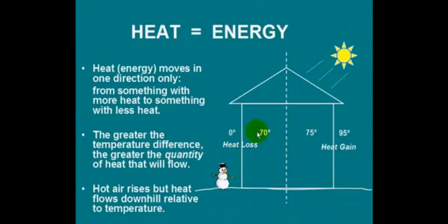In a situation like this in the wintertime, 0 degrees, you're going to have probably 62, 63 degree floor all winter long. The temperature of the air coming in from the ceiling could be 100, 110, 120, depending on how old the furnace is. That 100 degrees will go to the 60.